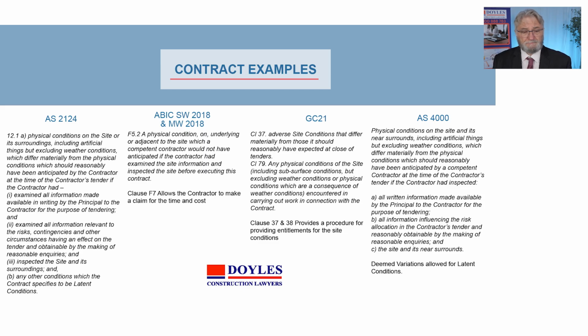It's worth having a look at the examples that are used in respect of latent condition clauses. If we look at AS 2124, its latent conditions are physical conditions on the site or its surroundings, including artificial things but excluding weather conditions, which differ materially from the physical conditions which could reasonably have been anticipated by the contractor at the time of the tender, if the contractor had: 1. examined all information made available; 2. examined all information relevant to the risks and contingencies, and other circumstances having effect on the tender and obtainable by reasonable inquiries; and then inspected the site and its surroundings, and any other conditions which the contract specifies to be latent conditions.